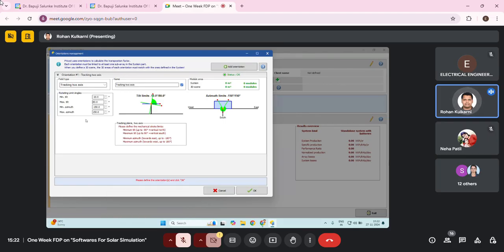So if your plant is very huge, megawatt scale or more, we can think about tracking panels. But if you are going for a 3 kilowatt plant with tracking, you need to be very careful: even if I am hitting the maximum 39% value, how much energy am I getting and how much cost am I paying? So we need to be very careful about selecting those things.